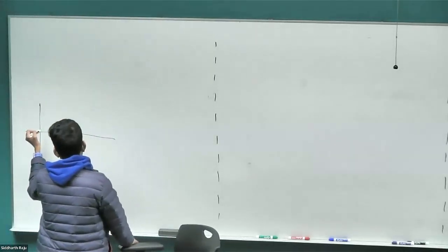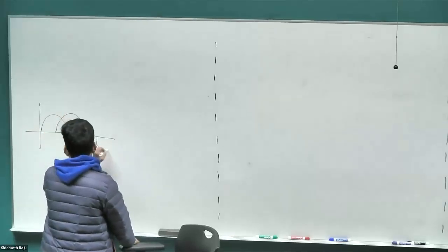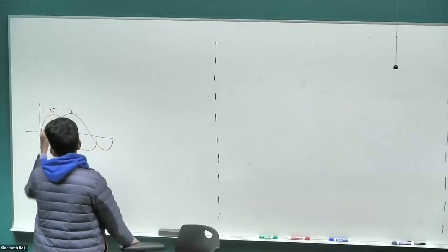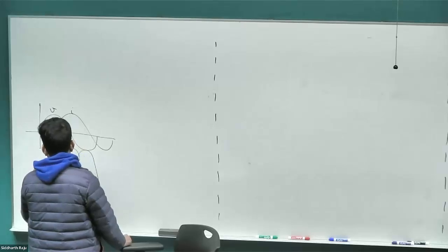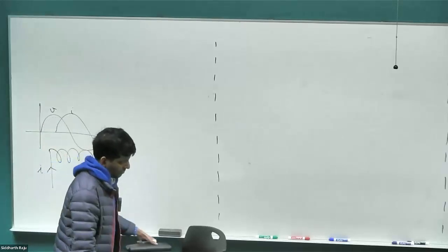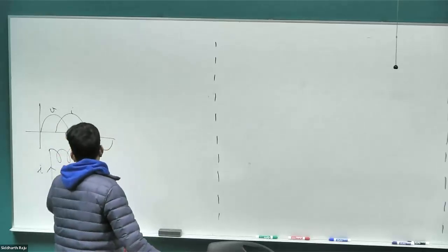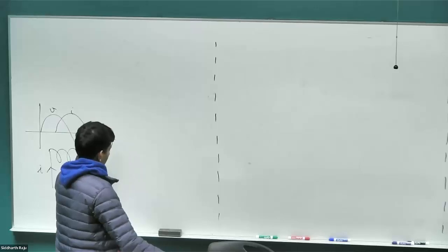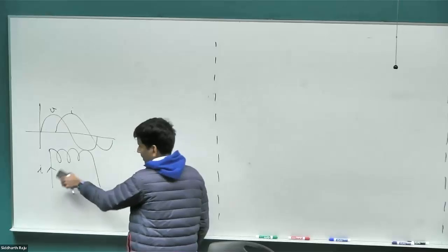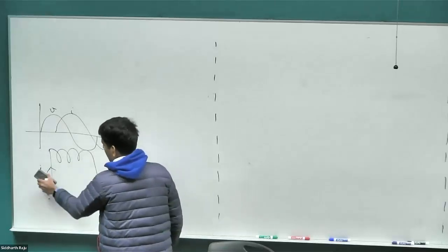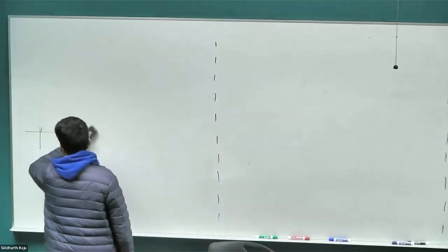For both the second problem and the last problem, we plotted the voltage and we plotted the current. But it only makes sense if you give what the polarity for the current is and then mark what the direction for the voltage is going to be. Because if I choose this positive, negative, it can look like this. If I swap it around, the same waveform can be negative. So just drawing this plot alone is not sufficient. Draw the inductor diagram and make sure you draw the voltage and the current along with it. Otherwise, I think everything else looks fine.